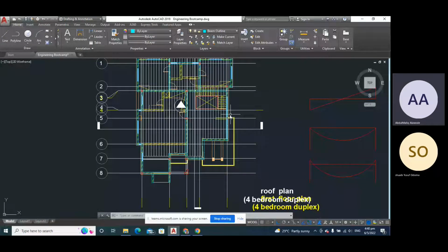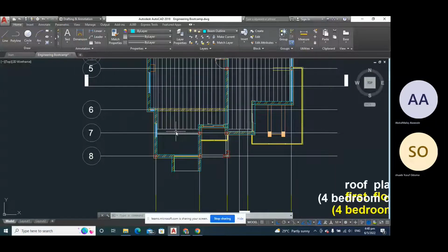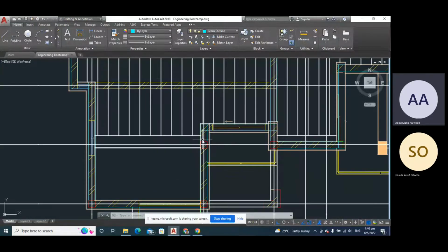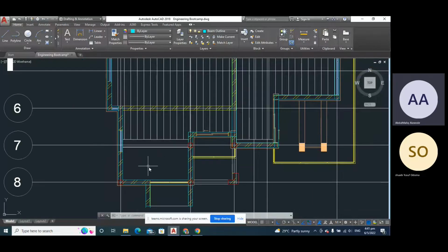Yes, here we have something here. I said this roof is one-sided; it drains to one side. So it is very important that we have an extra beam here. That beam is going to be an upstand downstand. What do I mean by upstand downstand? Because this place is obviously a slab on the roof, while this place on that same level is going to be void.